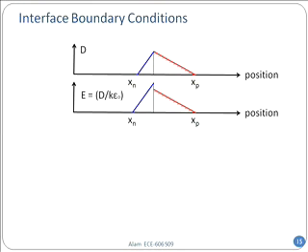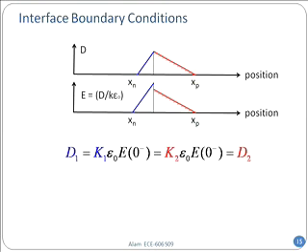That will depend on whether both sides are silicon or not. If it is different material, then you make sure that there is a discontinuity. Make sure of that. And this is the basic elementary statement that kappa 1 and kappa 2 essentially are the relative dielectric constants of the two sides, and you take care of that.